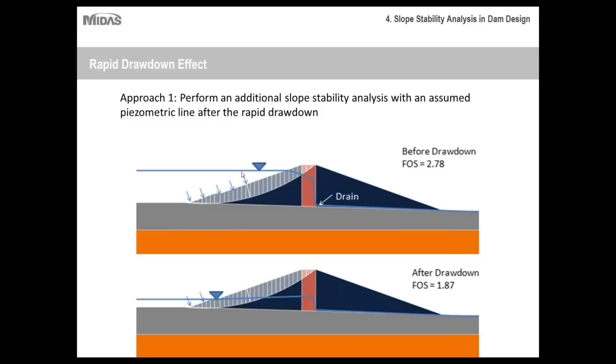of the water is actually helping to stabilize the slope, because of the way the water is acting upon the slope. It's sort of keeping it stable. Whereas if this water is taken away, the slope suddenly becomes less stable because it doesn't have that force acting downward upon it.